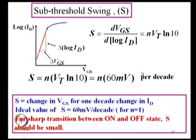Why do you say best value? When n is equal to 1, subthreshold swing is 60 millivolts. That is the change in V_GS for 1 decade change in I_D, that is the meaning of that. For 1 decade change in I_D, how much V_GS is required? Now, this is a very important parameter in MOSFETs, particularly when you go for low voltages.